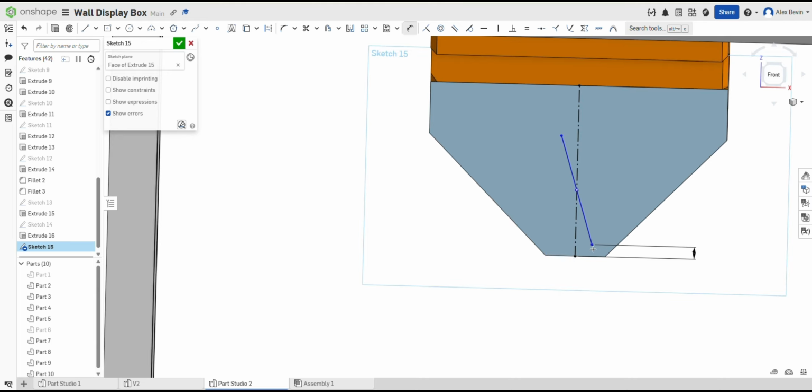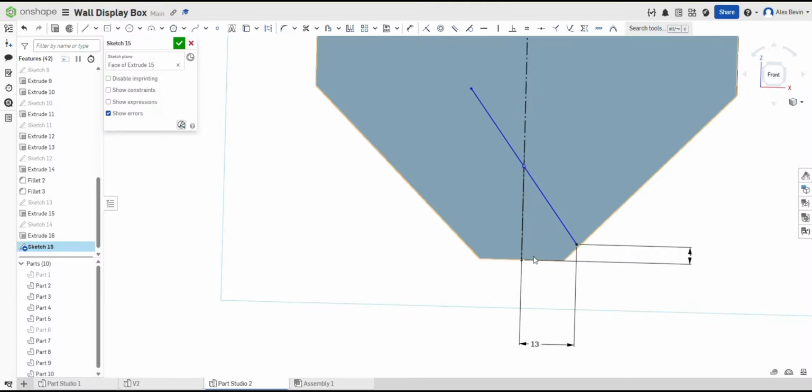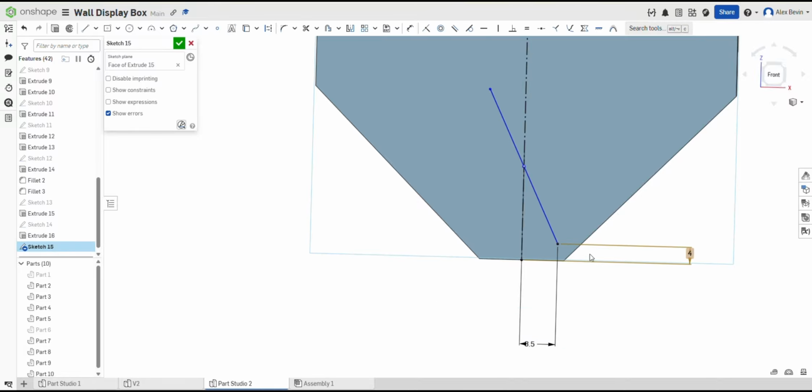Now set the countersink values. Use 3.8 mm and 10.5 mm with a 90-degree countersink. Press OK. That gives us clean mounting holes ready for an M5 style screw. And because it's countersunk, the screw head won't interfere with the box sitting flat.